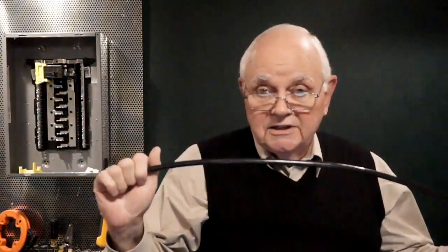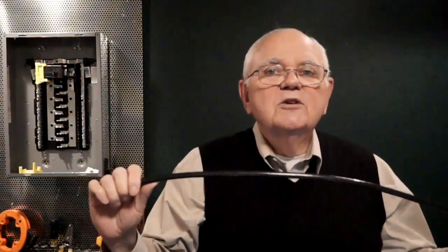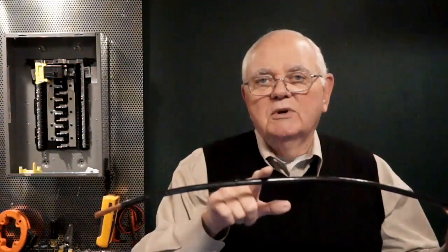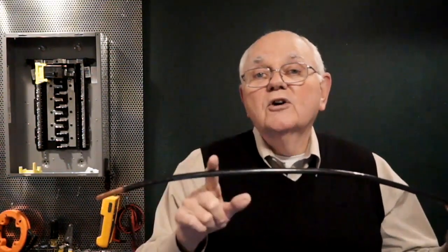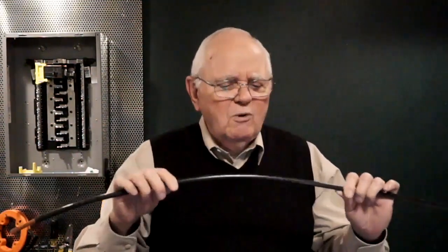So for a given amount of current flow through my conductor, the hotter it's going to get. In fact, it's an I squared R loss. We take the amount of current squared and multiply it times the resistance. So in other words, if I double the current flow, I don't get twice as much heat. I get 4 times as much heat. What's important to understand is that with a small increase in current flow, I can get significantly more heat being produced in my wire.